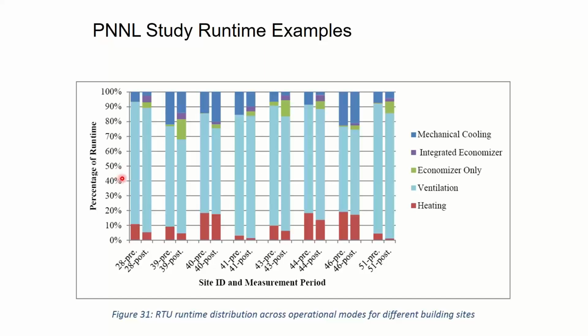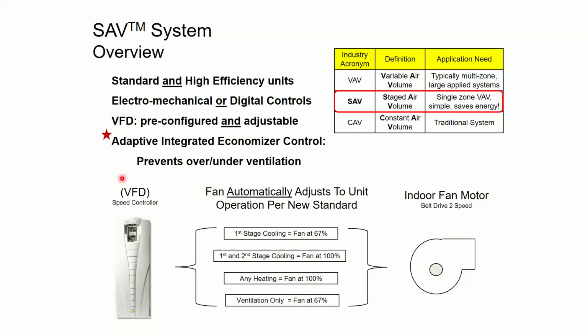So you start thinking about all this cool stuff we do to save energy and get better SEER ratings on our cooling systems and better AFUE on our heating systems. It almost kind of doesn't matter because the fan is basically the energy pig. So if we don't find a way to save fan energy, the rest of it is just little tiny baby steps. You can only save so much compressor energy when the compressor is hardly ever on. So we got to pick on the fan. So if you work for a fan manufacturer, I apologize. We're picking on you guys now.